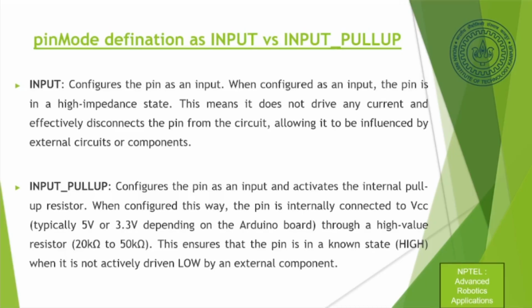Now, pin mode definition as input or input pull-up. When you say input, it configures the pin as an input. When configured as an input, the pin is in a high impedance state. This means it does not drive any current and effectively disconnects the pin from the circuit, allowing it to be influenced by external circuits or components. So any sensory signal coming from outside can come in.